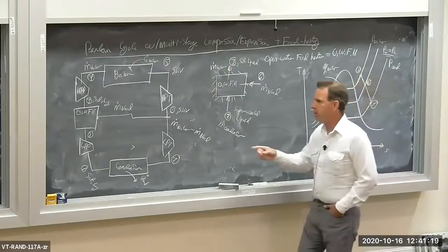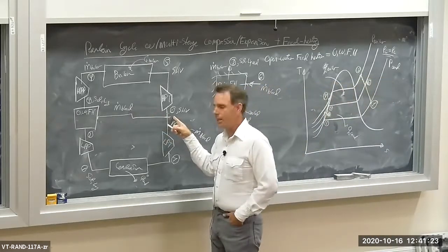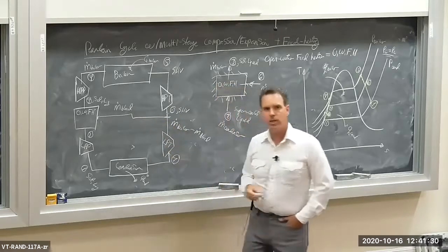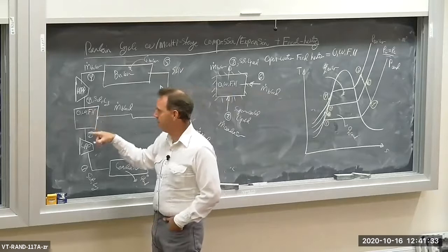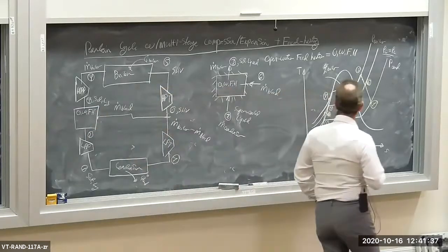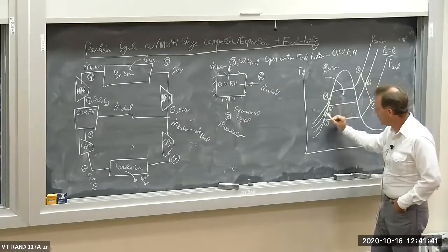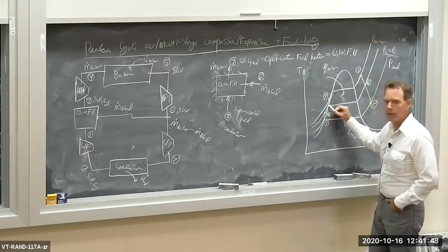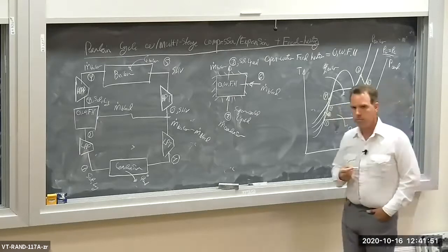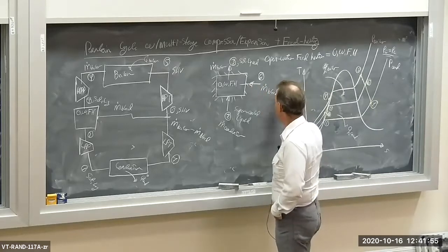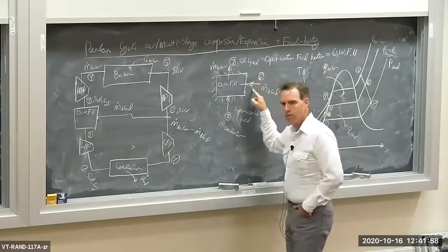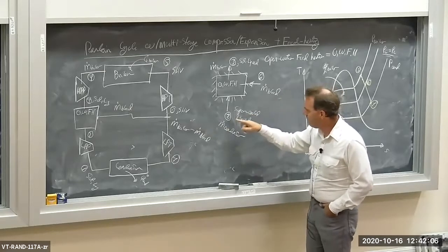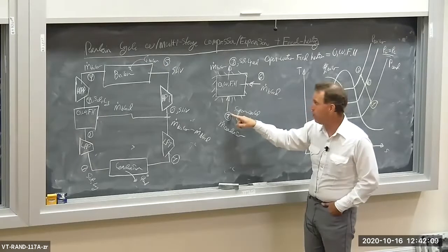Now we're going to bleed off just enough intermediate pressure, superheated vapor steam. We're going to bleed off just enough to heat up the liquid water to a saturated liquid at the intermediate pressure. So on the TS diagram, we're going to take a jump from supercooled liquid at the intermediate pressure to saturated liquid at the intermediate pressure. So we're bleeding off a certain amount of H2O from the exit of the high pressure turbine. We're going to bleed off a certain amount. We're going to mix it with supercooled liquid, which comes from the low pressure pump outlet.